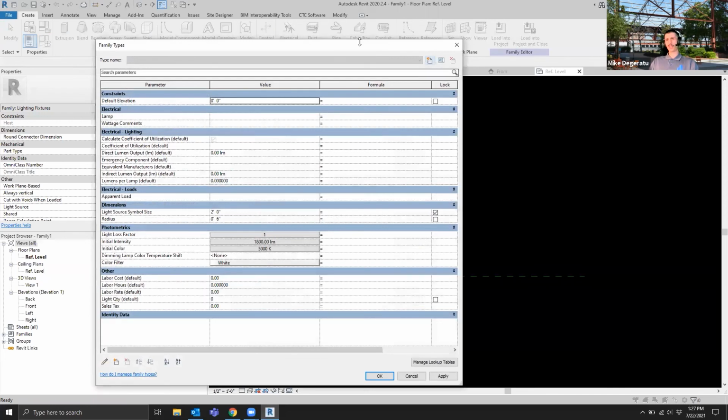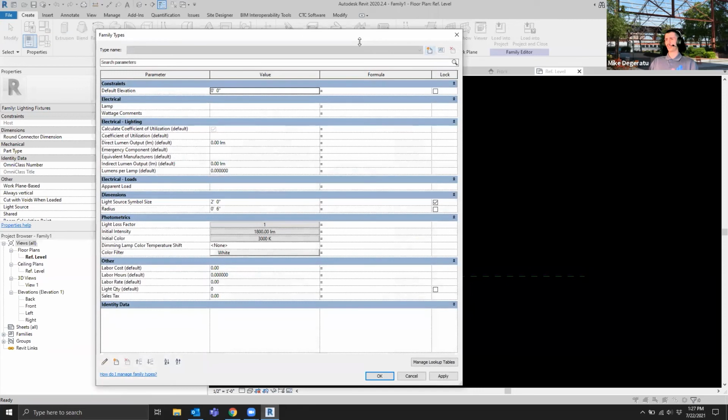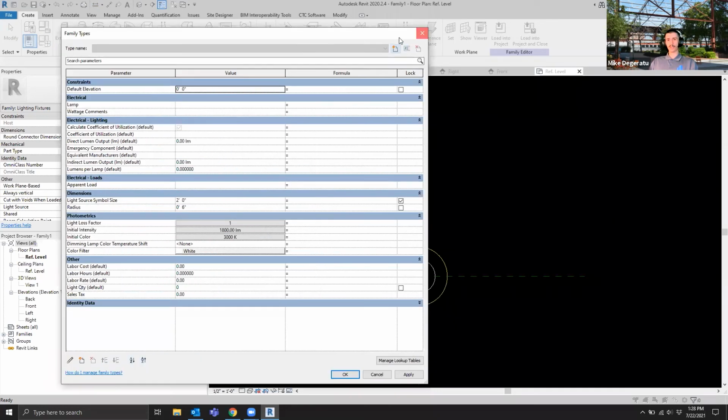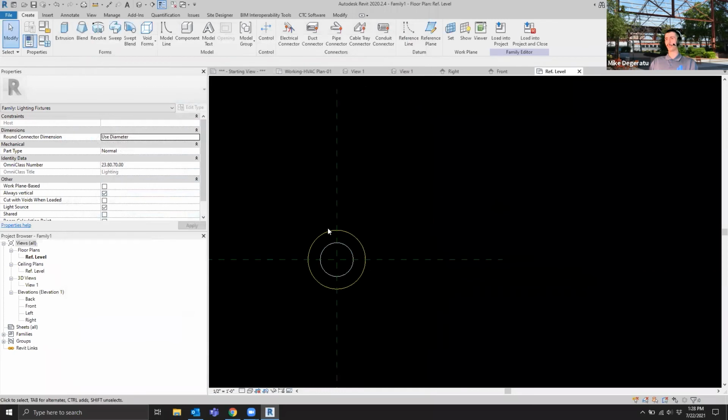Now, of course, if you're using this tool and creating your families, what you can actually do later on, if you decide you want to make a change and split things up differently on a different category, is do that easily. The only caveat is you would have to go through and delete the parameters in each family and then reload them for each one. And then your family will have all the parameters. You could load it into the project and see it there.